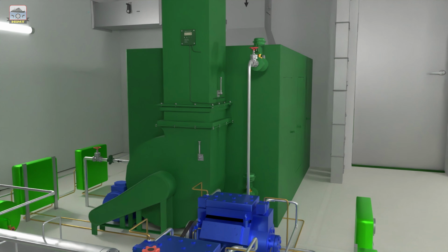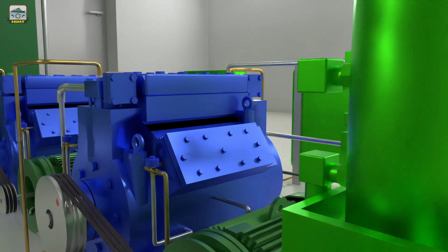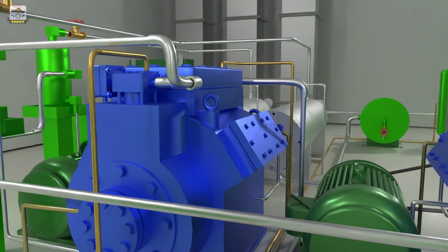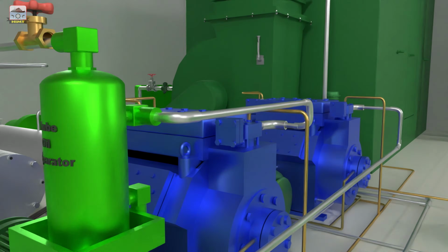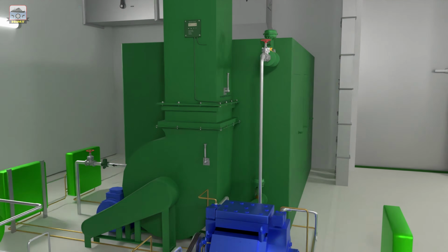For human comfort, the temperature is maintained between 22 degrees Celsius and 25 degrees Celsius, and relative humidity is maintained between 50% and 60%. The system must prevent the spread of fire and be designed with features like insect screens and quiet operation. The system must avoid producing objectionable noises or vibrations.